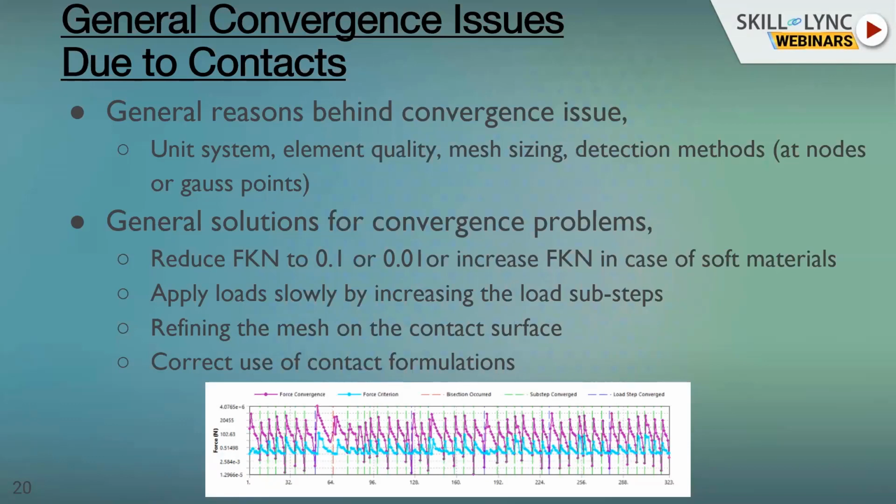So the mesh sizing should be fine enough so that the nodes on the contact, when they are coming and searching for the respective nodes on the target, are able to find each other, right? One node is coming, and where are the respective nodes? It wants to write the constitutive equation and transfer the force from one node to another, and if it is not able to find that node, it will penetrate into the body, right? So the nodes should be enough to transfer the forces.